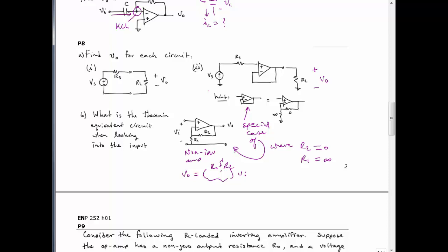Maybe it will retransmit it. Maybe it will turn it into something that will go out over a speaker or whatever, or display. But unless RL is infinite, which in any practical circuit can never be truly infinite, there will result some amount of voltage division, and therefore there'll be some voltage attenuation. And we oftentimes don't want that.